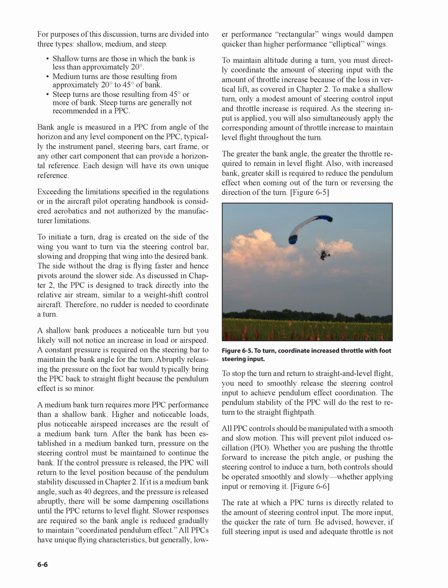Figure 6.5, to stop the turn and return to straight and level flight, you need to smoothly release the steering control input to achieve pendulum effect coordination. The pendulum stability of the PPC will do the rest to return to the straight flight path. All PPC controls should be manipulated with a smooth and slow motion. This will prevent pilot-induced oscillation, PIO.